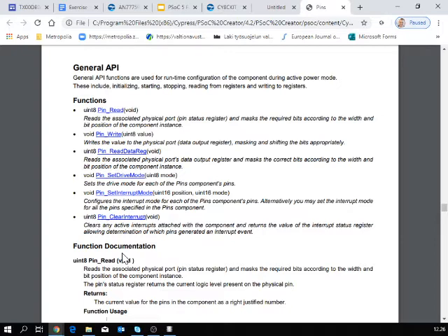For example, reading a pin would be done with this kind of function. But again, remember the naming convention. Now our pin is called LED1, so the corresponding function is LED1 read. But we are probably not reading that value, but more like writing, LED1 write.